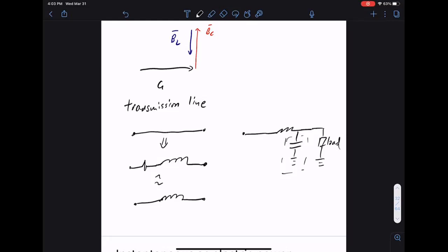What is the advantage of that? Is it like reducing the currents going through, or? This boosts the voltage, makes your voltage higher. So over a long line, your voltage seems to drop. A capacitor will boost the voltage. We don't have enough math yet. We'll get there next class probably to see why this is the case. Intuitively, this puts your voltage up, right? So often, especially if the line is very long, by the time you get to the end, the voltage magnitude tends to be low. And one way to boost that up is to put a capacitor there to support voltage.